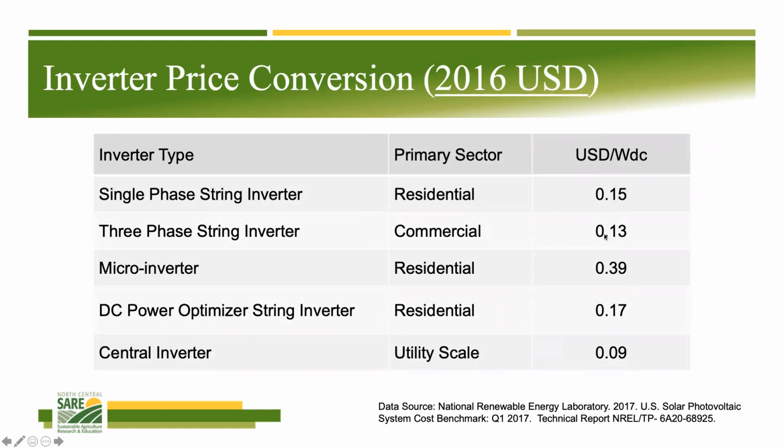And if we reflected on that last slide in 2016, that's right about where the costs were. Comparing it to the other technologies, obviously your single phase residential inverter is a little bit more expensive, but as we look at micro inverters, they're significantly more expensive. But John's mentioned some of the benefits, whether it's shading or panel level monitoring, meets Article 690.12 with the rapid shutdown standard. So a number of different features that you're paying for.